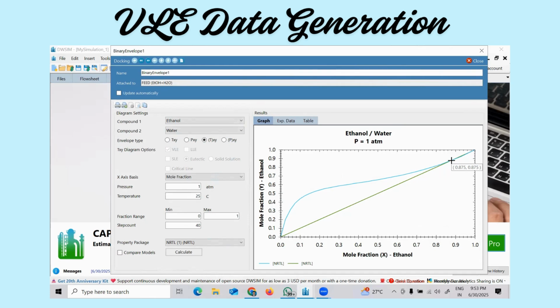In both phase diagrams, that is, one is the XY diagram and another one is the TXY diagram. For TXY, pressure is constant, and we have generated the TXY diagram, and we were able to identify the azeotropic point better with the XY diagram rather than the TXY diagram. That is also okay, but you have to zoom in and then find out. In a similar fashion, we can take another thermodynamic property package and generate such an equilibrium curve, and we can compare this azeotropic point with the given literature data. With the literature, of course, here it shows the azeotropic composition is 87.5%.